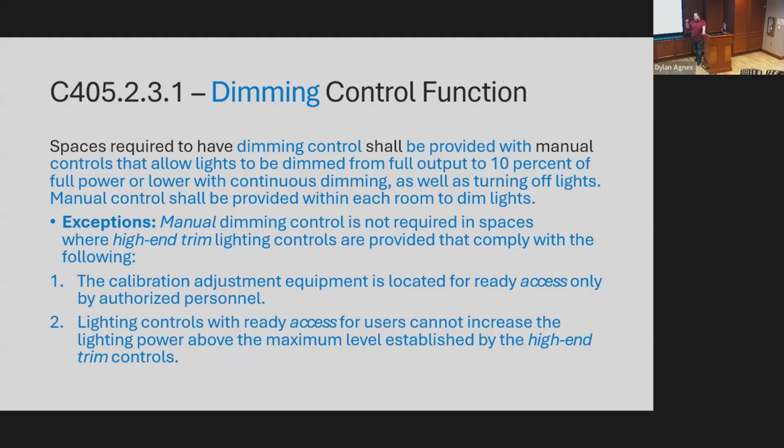But that's occupant comfort. Energy efficiency wise, we care about that because that's 10% of our load that is never realized, that we never use as long as that control strategy is maintained. And that's 365 days a year. You don't have to do anything. If a situation ever comes around where you need that 10% back, you have it. Now it's 110%? No, just because the new 100 was 90.